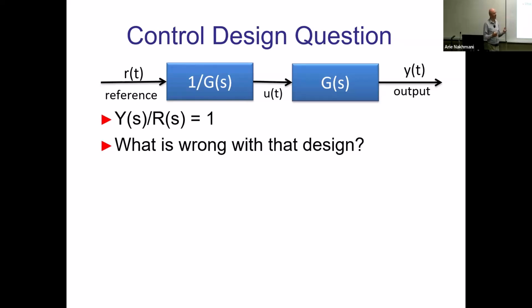So, what are the initial conditions of your controller then? They need to be exactly the same initial conditions. But they are 0 because you don't know them. Which means that this system starts from completely different initial conditions compared to this system. Right? So you obviously will get a mismatch between what the first system is doing and what the second system is doing.